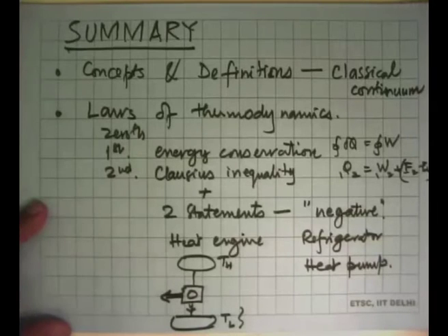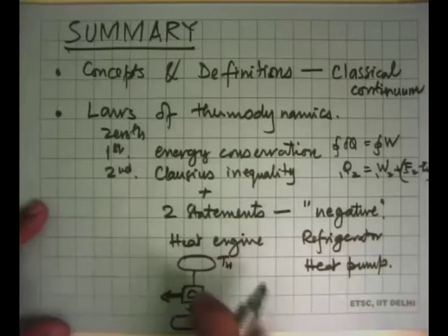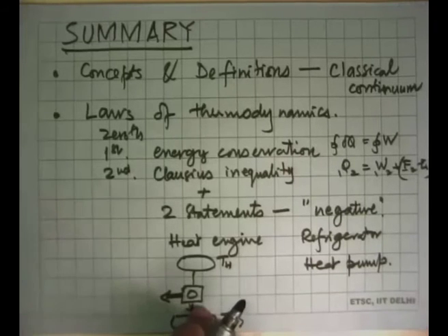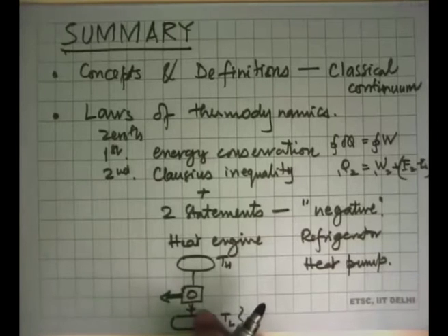And we made one comment though, that if this energy which is going out is used for other purposes like heating or cooling, then we can use that energy completely. We can say, for example, take steam from the Rankine cycle we just made and say, I won't expand it to 45 degrees Celsius, but I'll expand it to 80 degrees Celsius and use that steam for heating everybody's house or giving it for cooking.